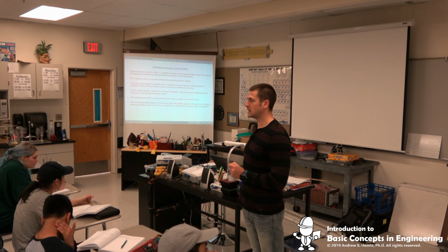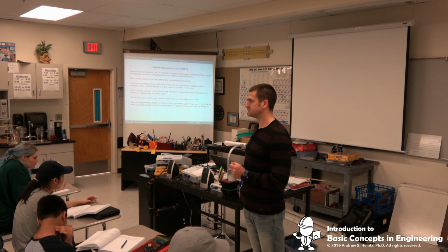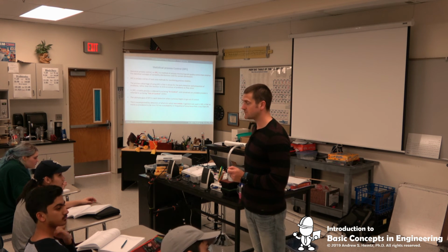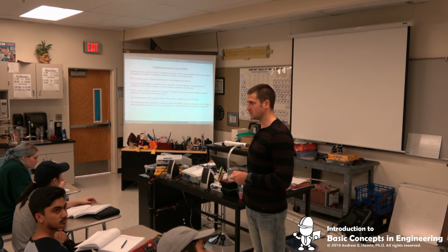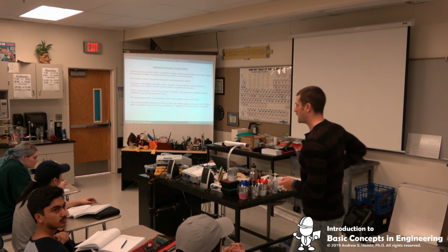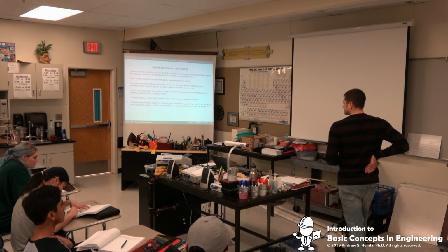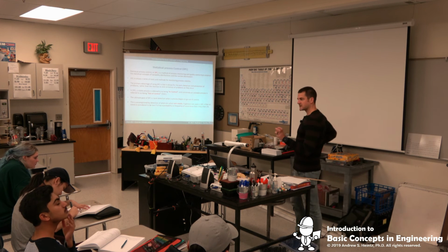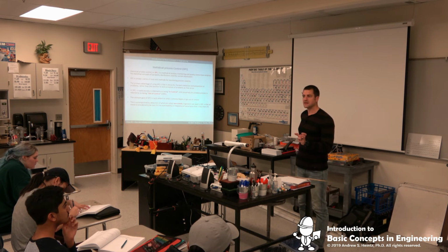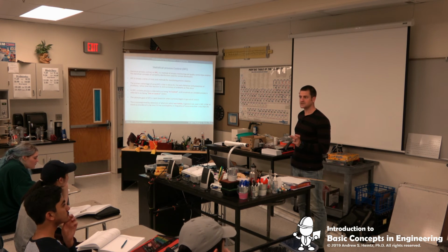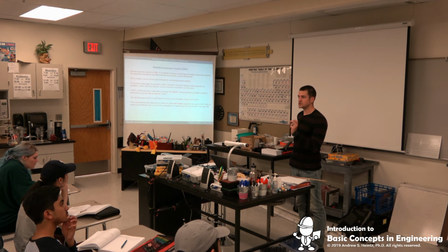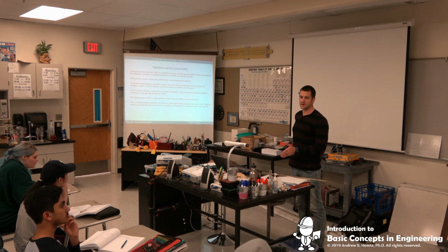0.3%, right? So that's a very rare occurrence that a normal data point falls outside of that range. So what we look for in SPC, as a general rule, is we actually expand it a little bit, but we look for an event that is statistically likely to occur less than 1%. Okay, so if we ever measure a data point that should occur less than 1% of the time, we say, whoa, stop, let's go in and figure out what happened with our process.